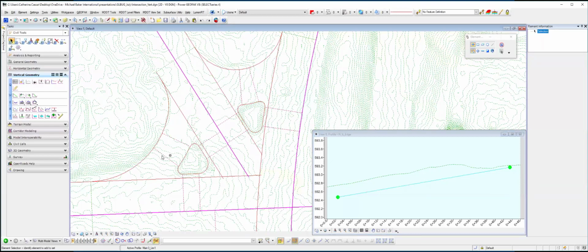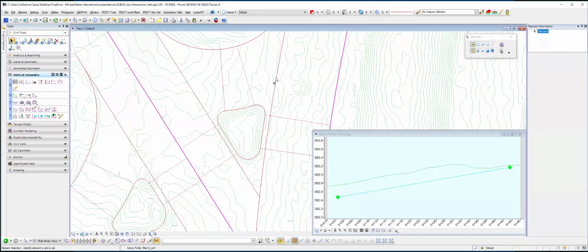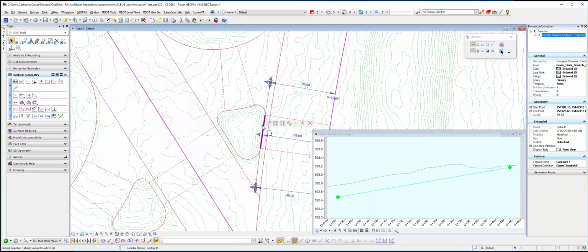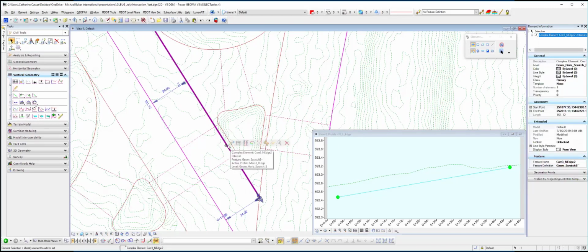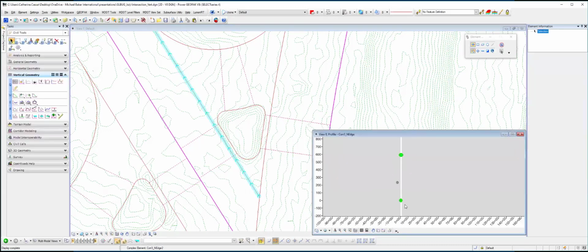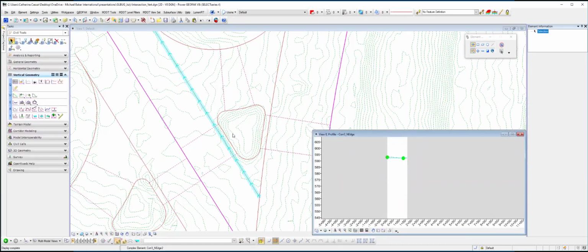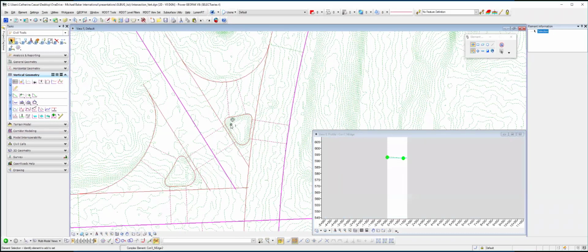In that case, you might want to do more of the same scenario that we did over here, to make sure you're transitioning this pavement a little bit more gently. This one would just inherit its profile from either this edge or the main line, depending on what you're doing. And then in here, we get into something a little more complex. I normally put these points in ahead of time, so we'll talk about these islands when we look at the surface model.